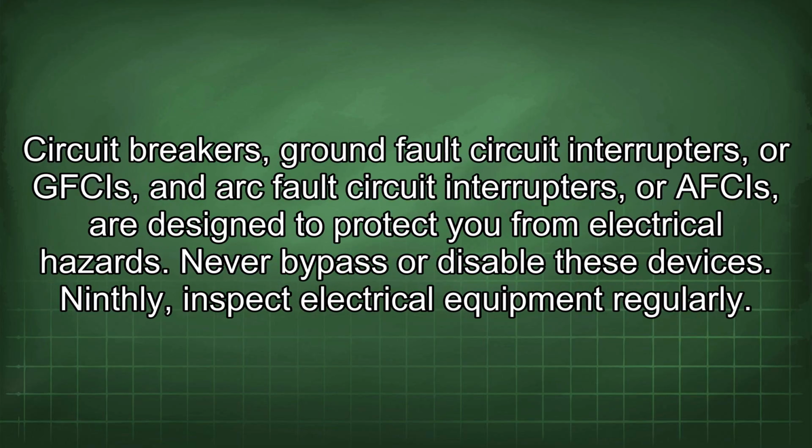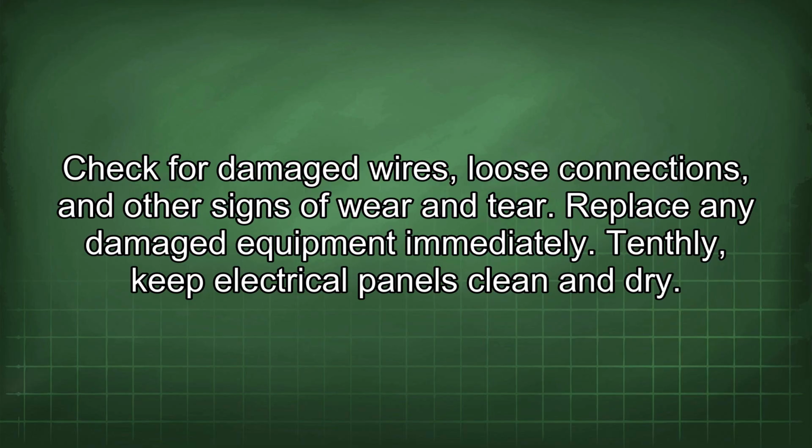Eighthly, never bypass or disable safety devices. Circuit breakers, ground fault circuit interrupters, or GFCIs, and arc fault circuit interrupters, or AFCIs, are designed to protect you from electrical hazards. Never bypass or disable these devices. Ninthly, inspect electrical equipment regularly. Check for damaged wires, loose connections, and other signs of wear and tear. Replace any damaged equipment immediately.